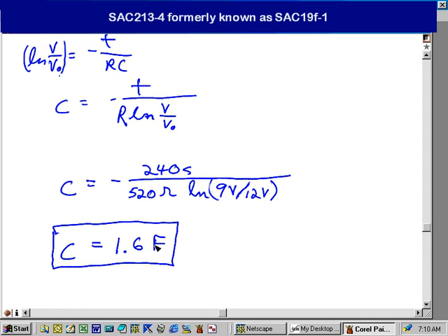So this is a design problem, right? An engineering problem where the engineer has to find out what capacitor needs to be used, and we find it's a very huge capacitance. You get a big capacitor that you use in the lab. I think it's 4,700 microfarads, 4.7 times 10 to the minus 3 farads, or 0.0047 farads, I believe. And that's a pretty good-sized capacitance for a circuit. This is just huge. Physically, that would be a large capacitor and very expensive.